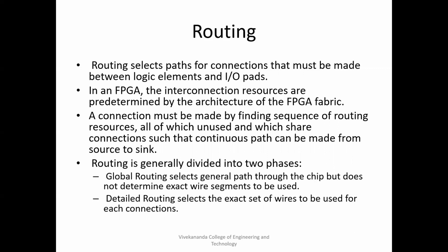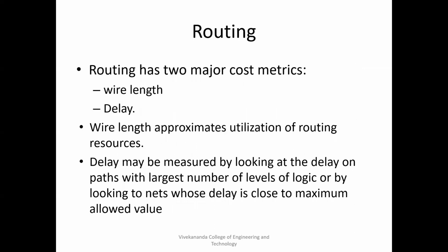Detailed routing goes into the exact detail, whether you should give a horizontal line or vertical line, how many steps through, or which blocks it has to move through, and how the two logical blocks get connected from one end to another. It is a detailed routing method.